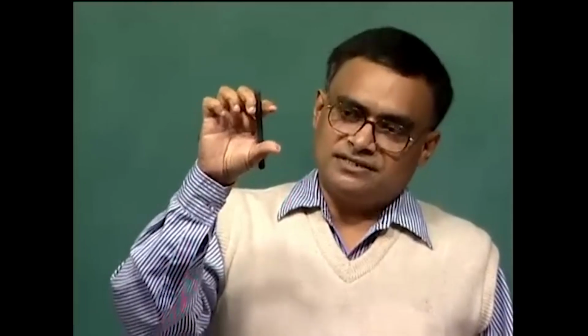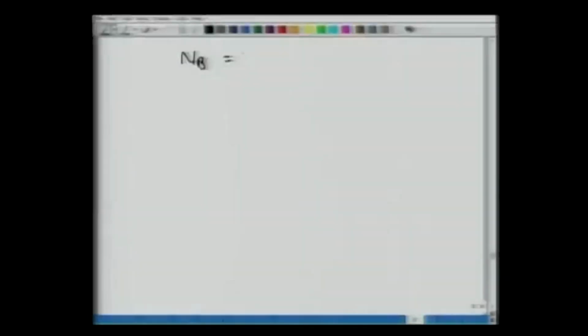In chemical engineering, and in so many contexts, you will see that we make this kind of approximation. Whenever we have two rates and one rate is much larger than the other, one can apply this quasi steady state. Here, the level of acetone decreases very slowly. Maybe when you do this experiment in your lab, you will see that it takes 8 to 10 hours, if not 24 hours, before you see a measurable difference in the height. So, assuming a quasi steady state, we can still apply the previous equations. Air is insoluble, so we can say that N_B, which is air, is 0, and we can apply the previous equations directly there.